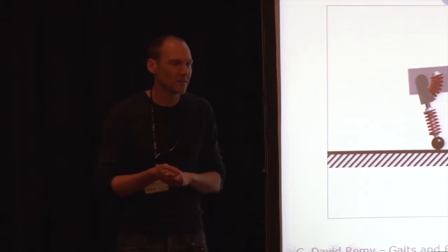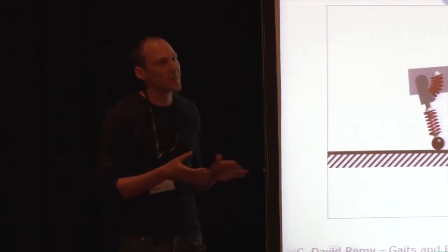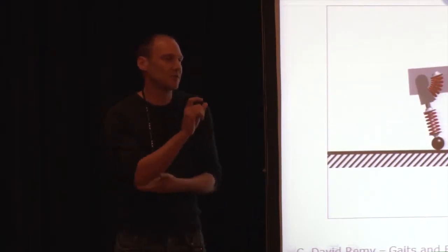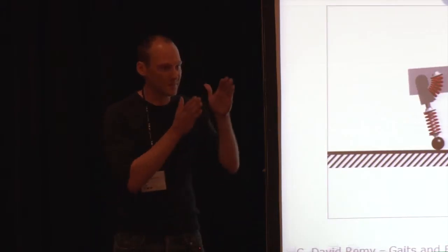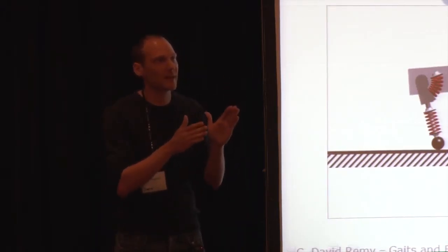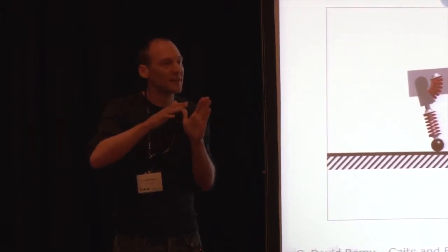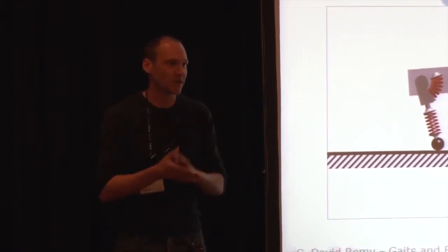So even when you have a leg mass, and you might think that it would be useful to balance the leg back and forth, you don't use a hip spring in your operation. Right. It's a serial spring. It might be different with a parallel spring. But a serial spring is basically only used to generate a certain force. So the actuator is moving with the leg, and at the point where the motion of the leg turns, you see a little bit of force or compression in the spring.